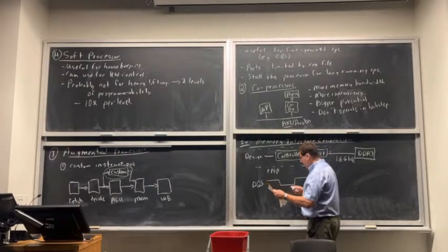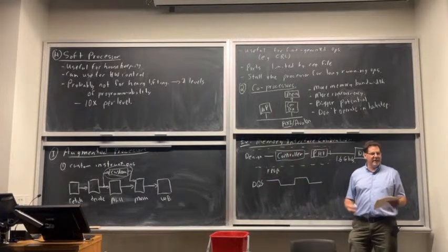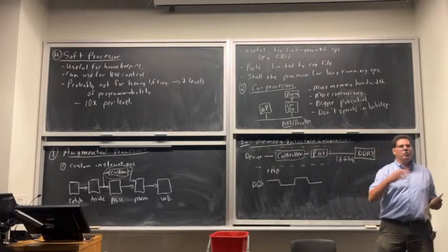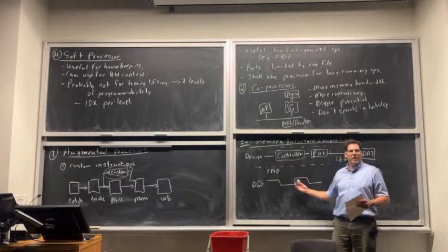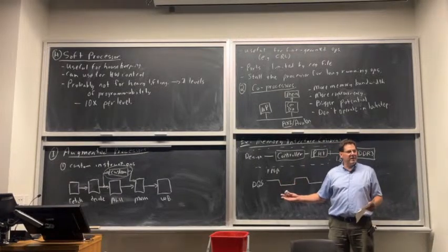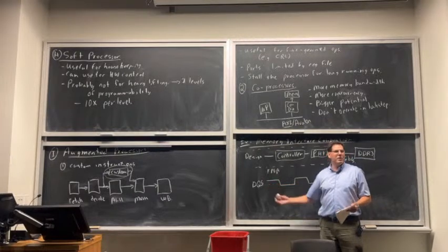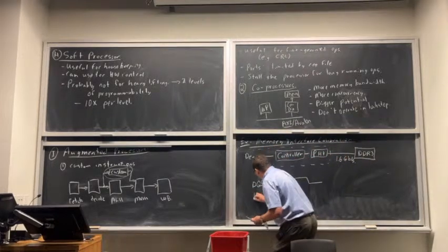So for DDR, you send DQS. DQ stands for data. S stands for strobe. Strobe is just a clock that doesn't run all the time. It can start and stop. To save power, if there's no data to transfer, they don't send this. There's no point in sending this strobe if nothing's happening. So it's like a clock that stops when there's nothing interesting happening. We call it a strobe.